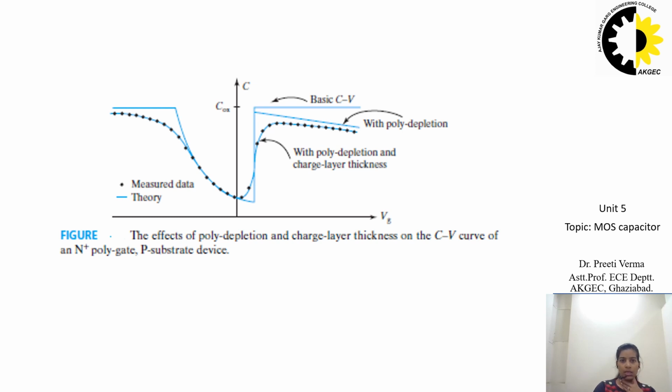It is valid to think that the bottom electrode of the MOS capacitor is not exactly at the Si-SiO2 interface. The capacitance rises smoothly towards the oxide capacitance because the inversion charge is not located exactly at the silicon oxide interface, but at some depth that varies with Vg. At larger Vg, C poly cannot be assumed to be infinite and C drops.